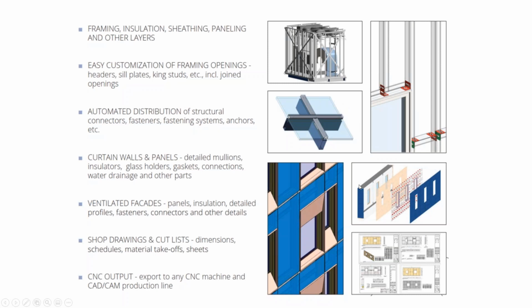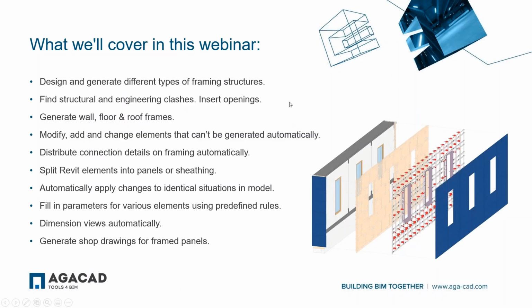You can also create different ventilated facades and create different rules for your openings based on their size or position on the wall. You can easily document everything in a matter of a few seconds or minutes, and everything will be ready for CNC production if needed. In a few clicks, it's possible to export everything for CNC production really easily.